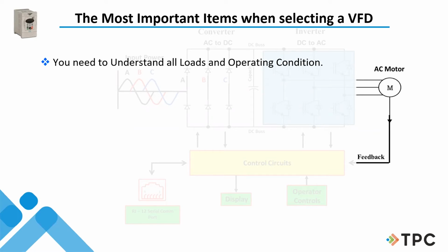So I need to go out there and put amp meters on it and check it for, I don't know, however many days you need to make sure it's gone through all the different cycles that it goes through. Do I need feedback? I don't know what this motor is and how important the speed is, but it might be.